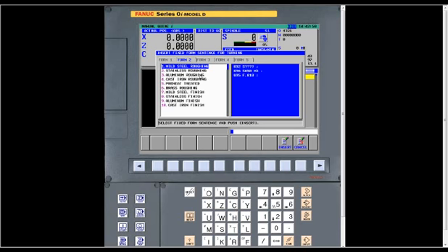And what I do in Form 2, usually I set up cut speeds for different types of material. As you can see, I've got mild steel, stainless steel, aluminum, cast iron, preheat treated, brass, roughing, and then finished feed rates and cut speeds for that also.